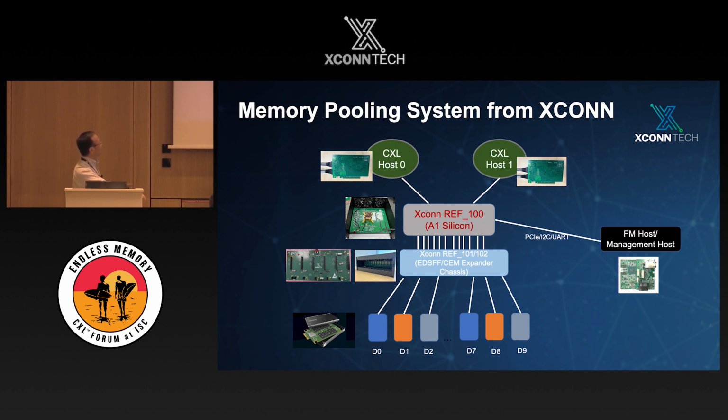We've also built some PCIe CEM slot expander or EDSFF expander boards to enable the downstream ports to be populated with many more CXL memory devices. And on the management host, we use a small board powered by an ARM processor, running all this fabric manager software.